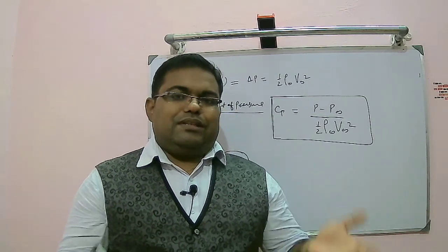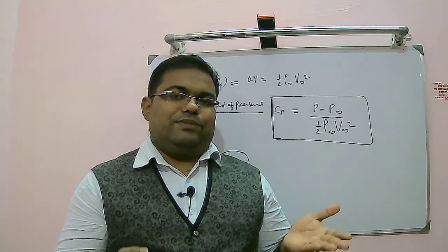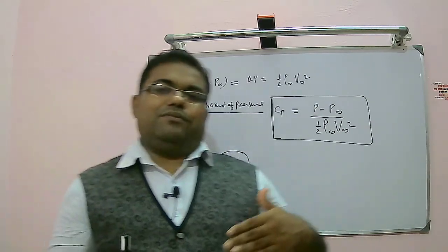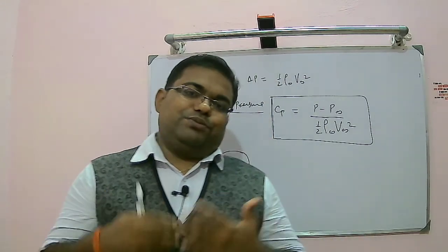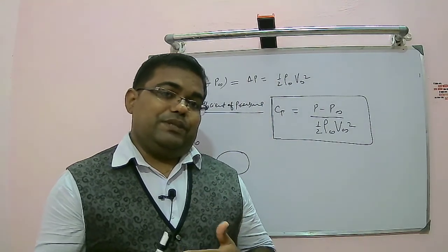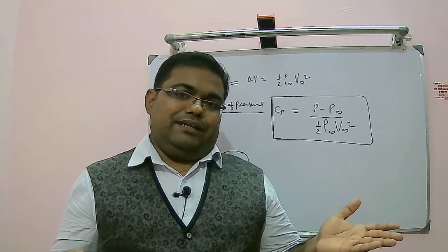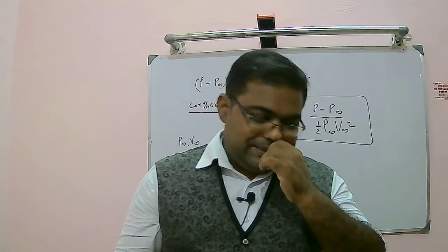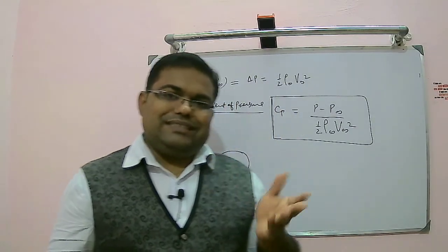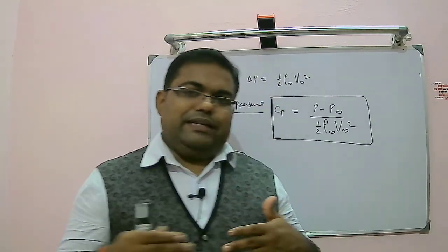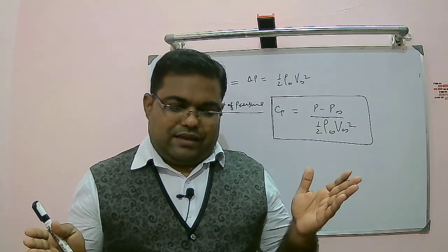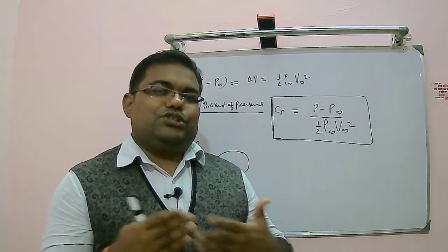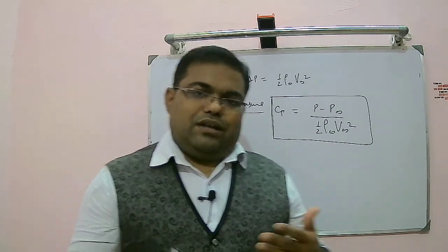Because of the boundary layer formation your flow will get attached, and after traveling over a certain length of the surface, flow will not have sufficient energy to stick to the surface, and it will separate. The moment it separates, it will form some sort of vortices at the backside, that is called the wake region. Alright, so basically our idea is to identify the location of the separation point, as well as the area of the wake, and how to minimize that. That idea you will get from the pressure distribution of a particular object.